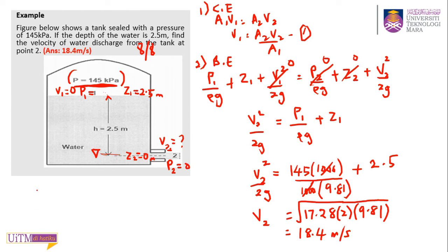You can only cancel out if the points are on a horizontal line, usually. Your point 1 and point 2 are together here. So this is what? The same position horizontally. That means your elevation is the same, so you can cancel out the z term for both points.